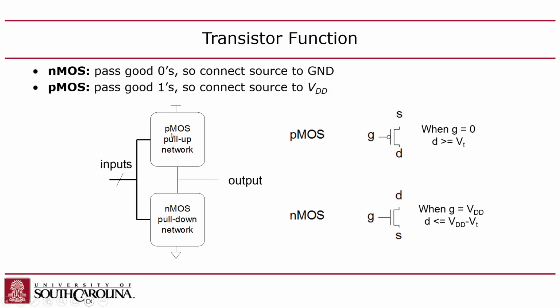So the pull-up network and pull-down network are mutually exclusive because they're complementary in a logic sense, right? So whenever you put inputs on the gate, you're guaranteed that only the pull-up network or the pull-down network will be turned on, right? And you're also guaranteed that exactly one of them will be turned on. Does that make sense? So you might say, well, how do you guarantee that? Well, it comes down to series and parallel connections of the transistors in those networks. That's really what it comes down to.